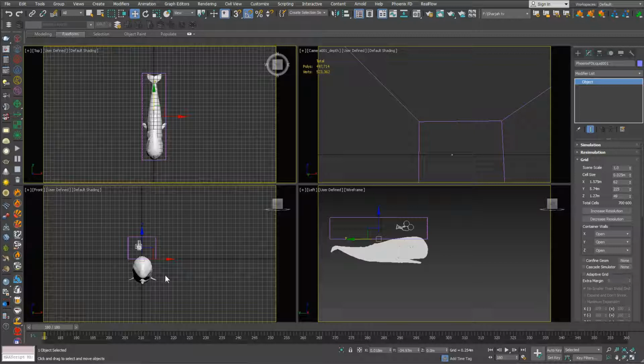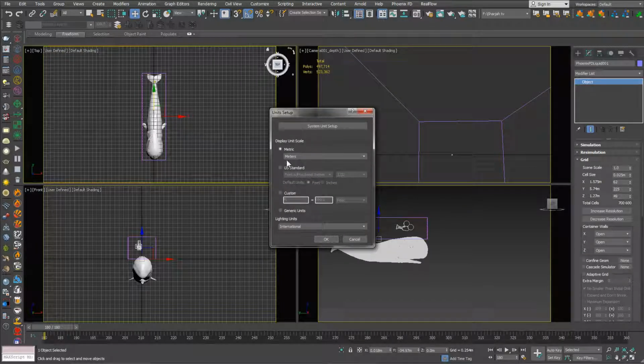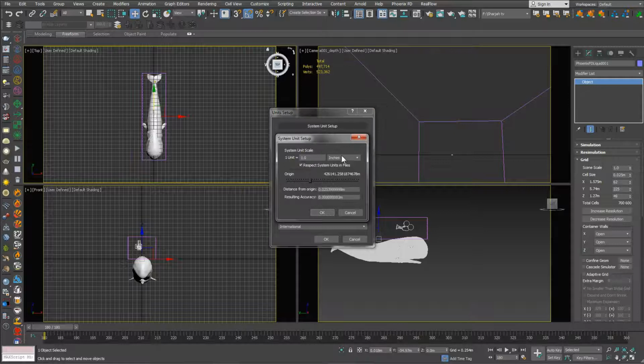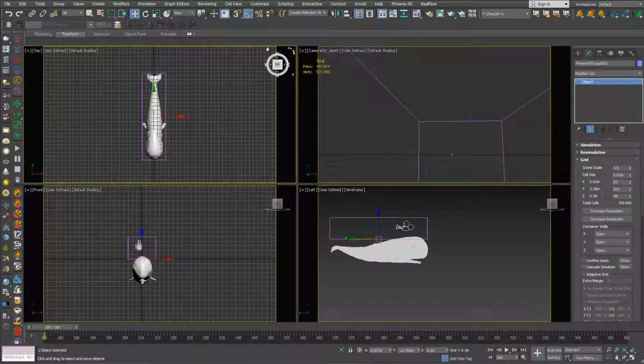And this spares us from even doing any modifications here on the model or the geometry and trying to retain the right scale. But if we want to change this, one way to do it, because now it's not 5 meters, actually it's like 10 meters to 12 meters, I can go to units here, change this to meters because I want to see everything in meters, and this is just for display purposes as you can see here. But I can go here and change this into centimeters, as an example, and try to see again. As you can see, this is 2.5 meters almost, or roughly.